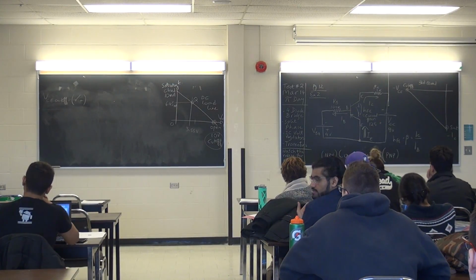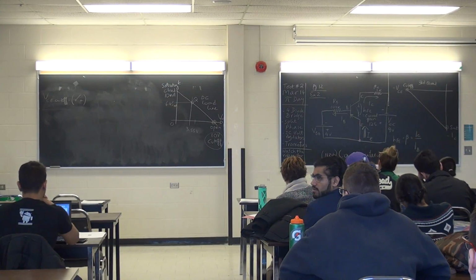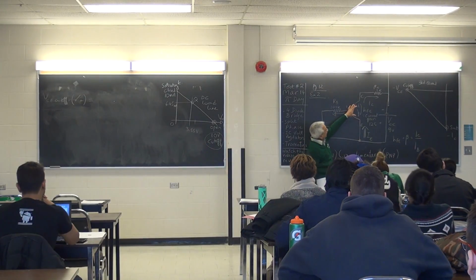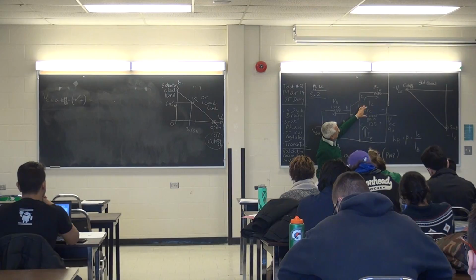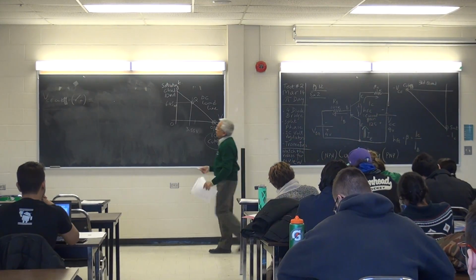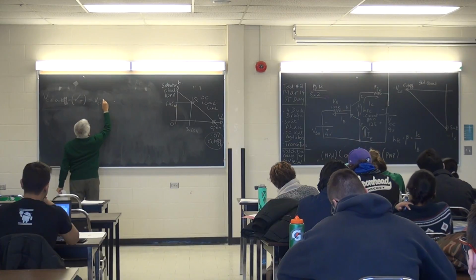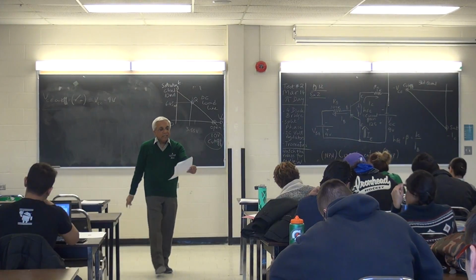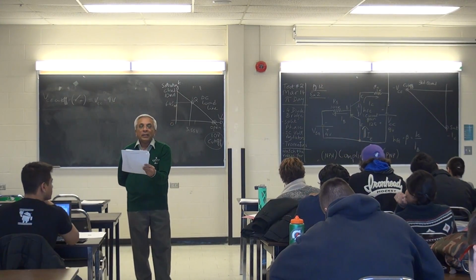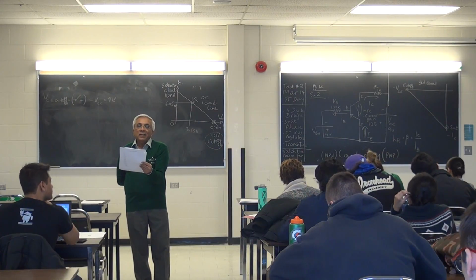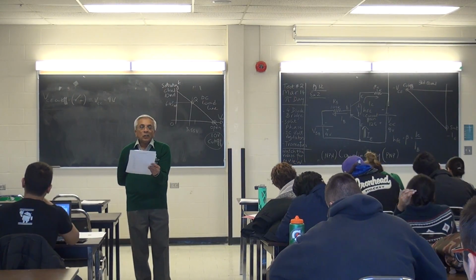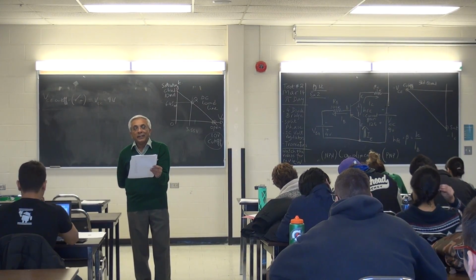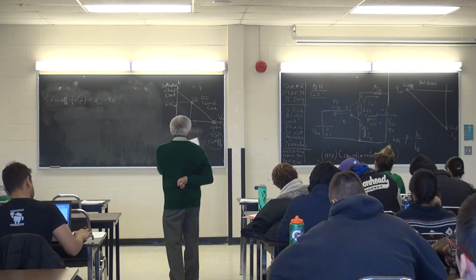So let's put a symbol of an open switch beside my VCE cutoff. If this transistor acts like an open switch, then the voltage from the collector to the emitter would be equal to the source voltage. So that's VCC, so that's 9 volts. Now, what I want you to read is the note at the top of the page which says, for the PNP circuit, do all your calculations as if it is an NPN circuit. Simply change the polarity of the voltages and currents after the calculation.